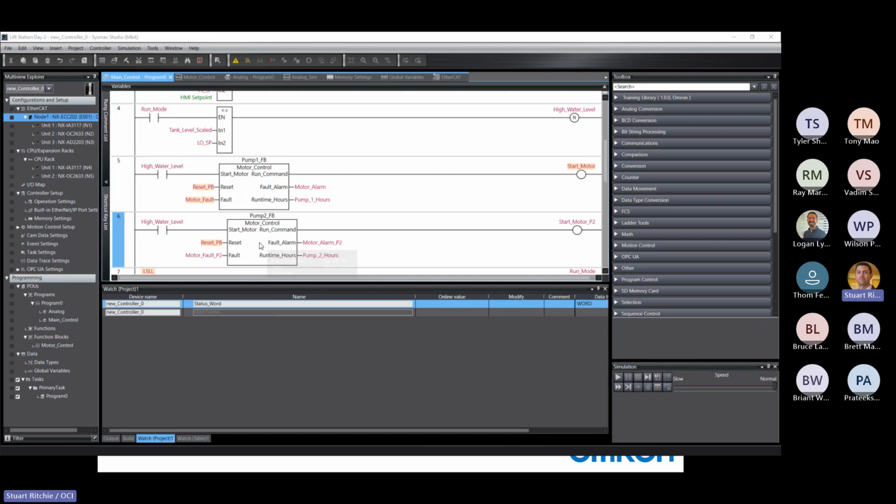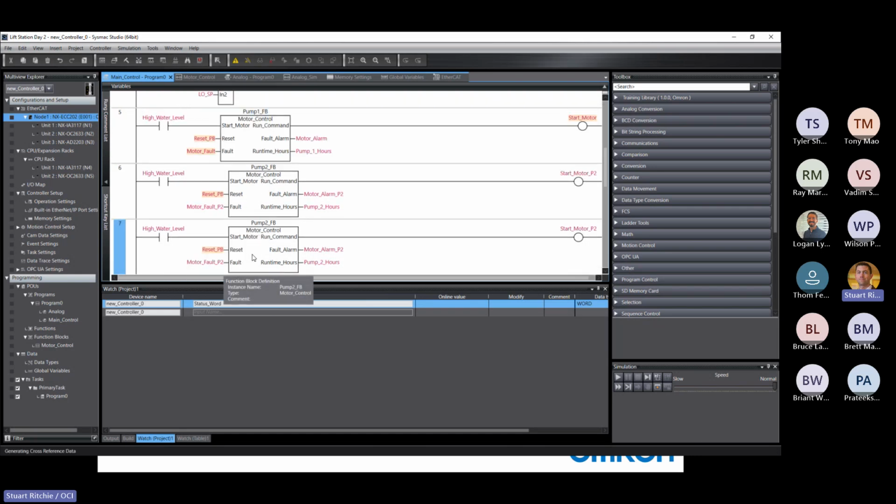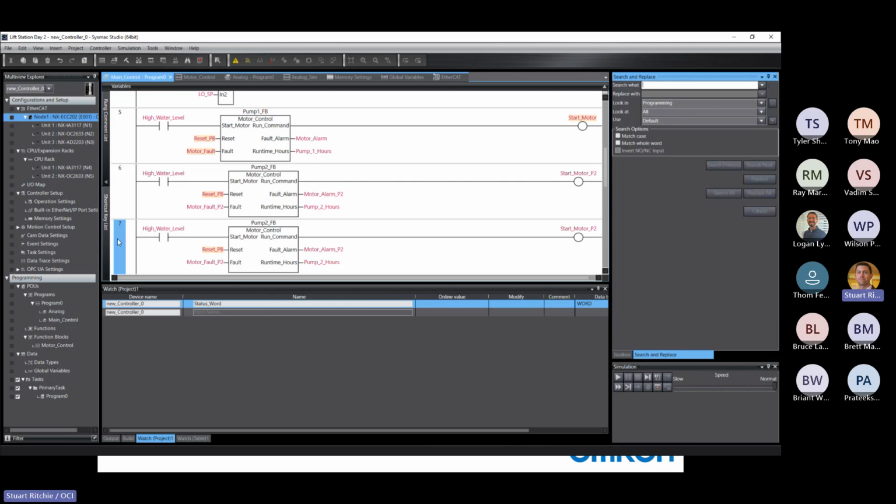Now, another tool that we can use to speed up our development, now that we have this tagged with a 2 in all of these tags, and you guys can play along with this or not, it doesn't matter. If we added a new rung and we do something called a search and replace, so Control F brings up your search and replace.